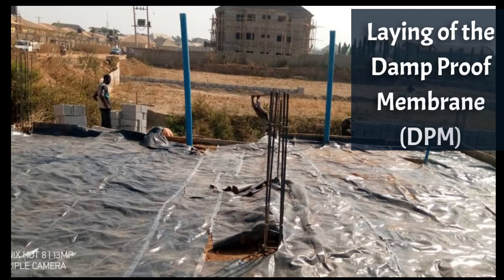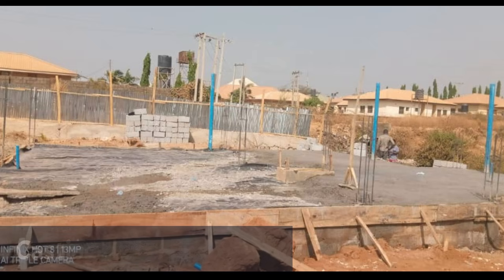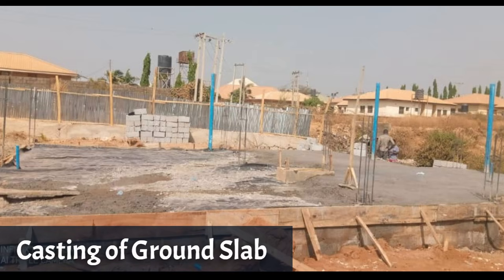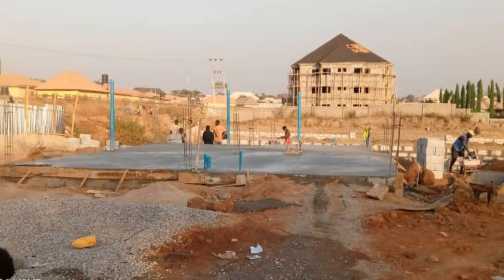Laying of the DPM, that's a damp-proof membrane, which prevents moisture from rising through the ground slab. Then finally, casting of the ground slab using a very good mix. This slab is also known as DPC or German floor and is poured over the entire building area. And that brings the end of the first stage, which is the foundation stage.